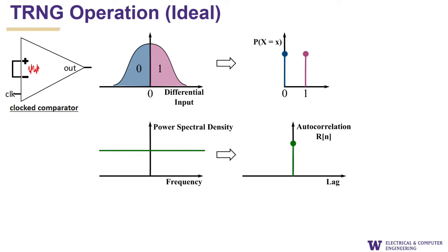If you're able to truly exploit this infinite frequency range power spectral density, the signal that you extract will be unbiased. In other words, the deviation from the probability of generating a 0 or a 1 is basically 0, it'll be 0.5. So no bias. And the autocorrelation of that signal will be a discrete delta. In other words, there is no impact of history.